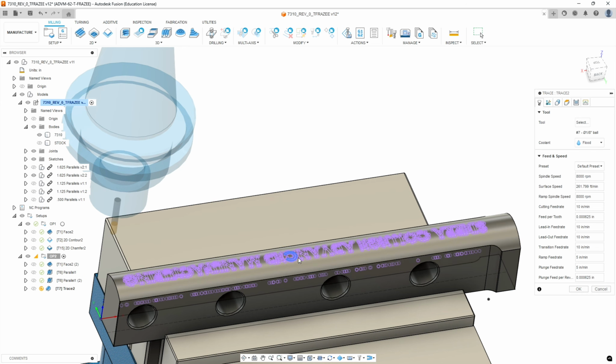We are going to just skim the surface, and then due to how light we need to go to have this text show up, we're going to just adjust that at the machine till it's barely cutting in the surface. So I'm going to have you program this so that the text is right on the surface, and chances are there's going to be enough variance between the cutters that you may get it engraved just fine with that, or you may need to adjust this cutter down at the machine, and that's a reason to have this as the last routine as well, so we can restart it. Okay, so we're going to go 8,000 RPM. I think we'll just leave the feeds and speeds as they are.